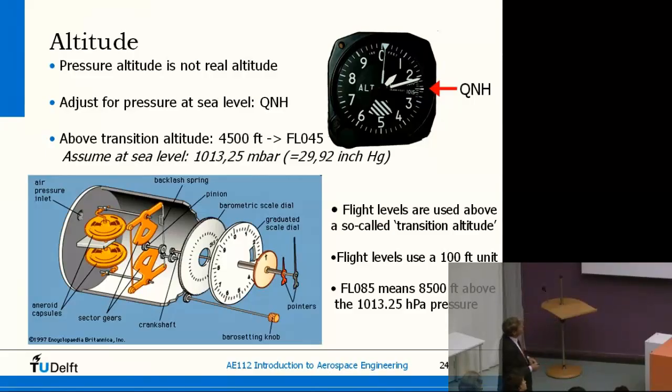Then when you take off, at some point, around 4,500 feet, they will say that is the transition altitude. It should be in the same message, you should have the transition altitude, and that's the altitude at which you change to the standard sea level, and then the pilot has to dial in 1013.25 hectopascal pressure as the reference, or 29.92 inches of mercury if you have that kind of setting on your instrument. In our airplanes, most of the time the SI units are used here.